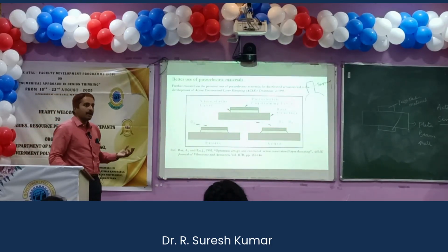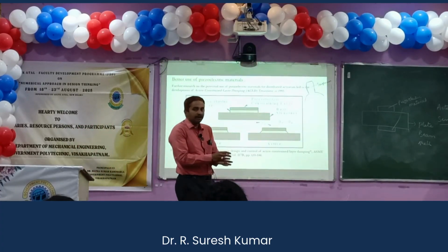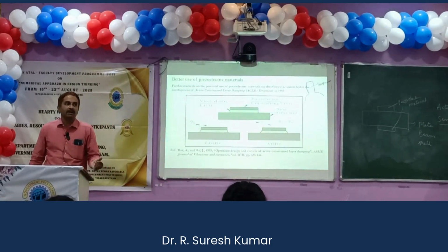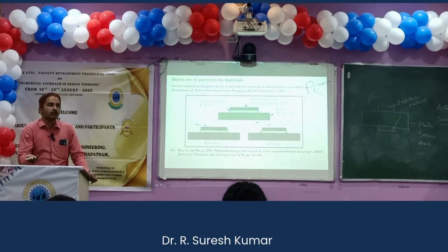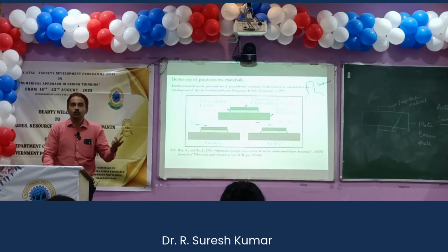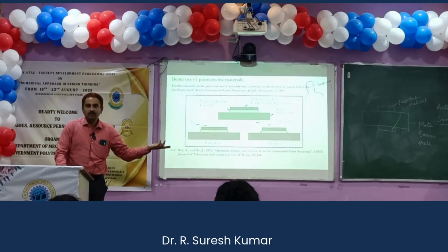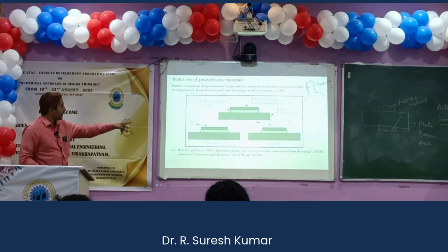Active constrained layer damping treatment is a combination of two materials: a smartness-adding material like a piezoelectric material, and a viscoelastic material. So what is a viscoelastic material? A viscoelastic material has the properties of both solid and fluid. For fluid, it follows Newton's law of viscosity, and for solids, it follows Hooke's law.